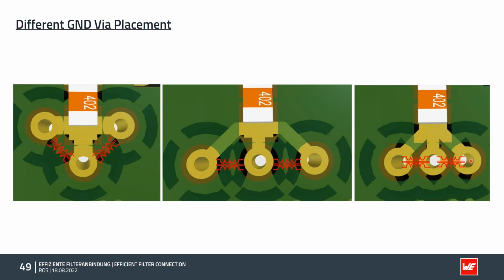If you put the wires close together, then the mutual inductance is increasing. The coupling will get a little bit higher. And because the current is flowing in the same direction in each wire, you get the proximity effect as a result. And for this, the inductance is not decreased so much as we would like to have in comparison to this construction.